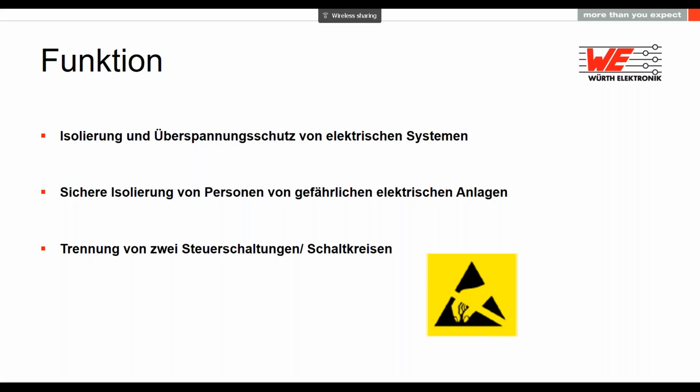But you also need the feedback from your charging device, how this is working or when I have to shut down. In most of these cases, an optocoupler helps, divides the two parts, and gives you the nice feedback to your main charging circuit.